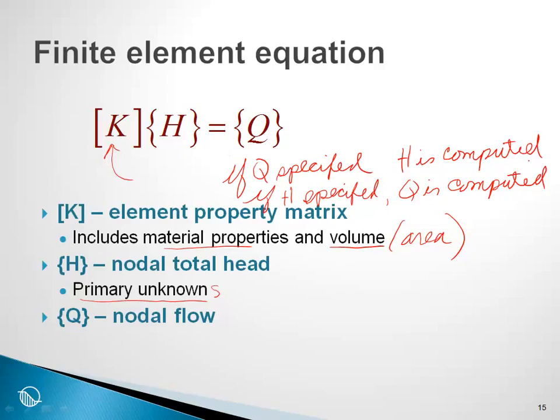Time and again, when we define boundary conditions, it is important to recognize that if I specify the head, I will compute a flux, Q. If I specify Q, the flux, I will compute a head.